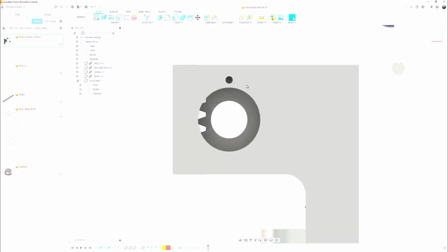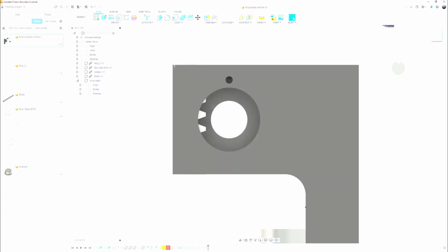Now that 0.25 depth plus the thickness of the cover plate, let's see here, it was roughly 0.33. So 0.33 plus a 1/4 inch is roughly a 1/2 inch length, 8-32.